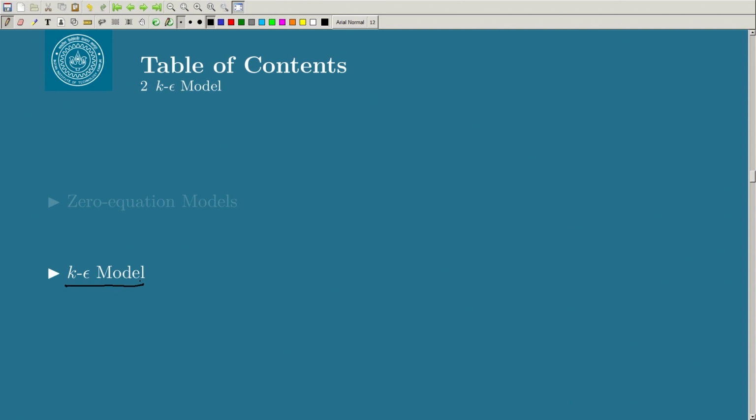So, there are so many k epsilon models; a few are like the standard k epsilon, which is popular, okay, and then we have RNG, okay, and then you have realizable, okay, and these are basically the eddy viscosity models. Then you have this cubic k epsilon also, okay, but this is not just eddy viscosity, this is a non-linear eddy viscosity model. Okay. So, here the viscosity is not only linearly dependent on the velocity gradient, but it may also depend quadratically or even on higher powers of the velocity gradient.